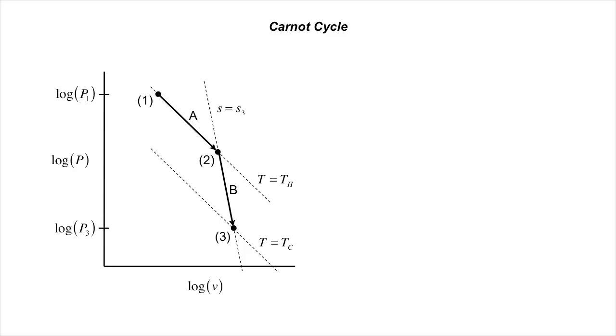One thing you might wonder is how Clapeyron, who didn't yet know about entropy, derived the transformation path from state 2 to state 3. But even without entropy, if we imagine the gas remains in a continuous state of internal equilibrium, with well-defined pressure and temperature obeying the ideal gas law, which is how reversibility was originally defined, we can still solve it. The key is to recognize that without heat, dU is equal to minus dW along the transformation path. Thus Cv dT is equal to minus P dV.